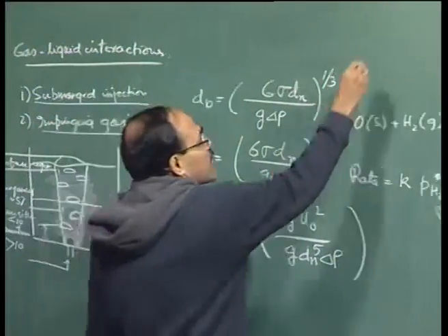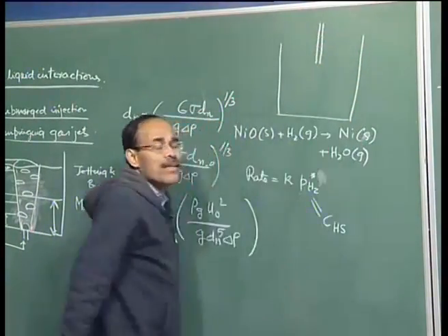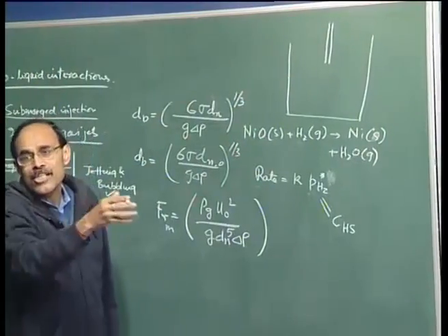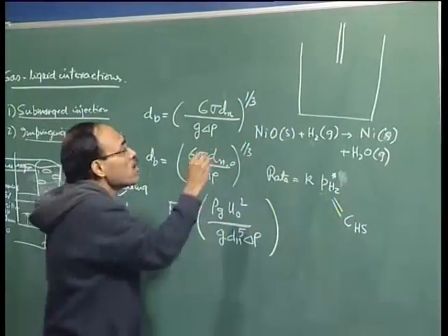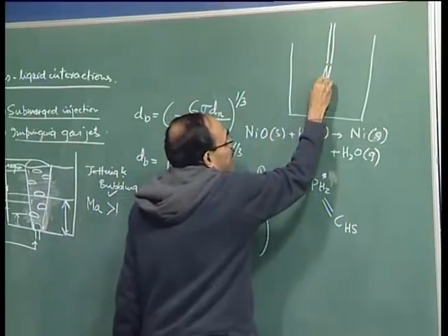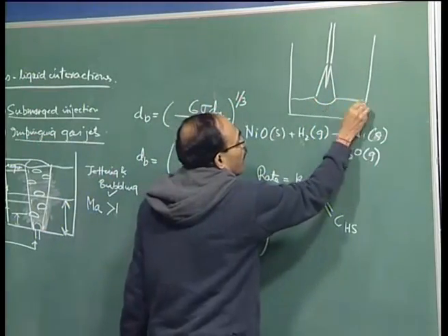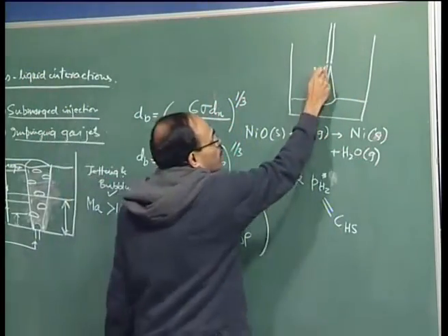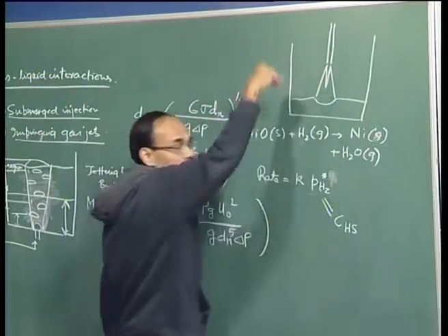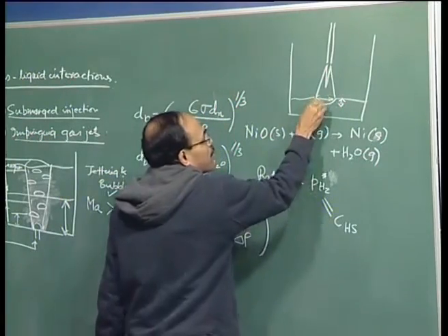Finally, very briefly, about impinging gas jets. When you have impinging gas jets on a system, for example a nozzle, particularly in an LD converter, you have different kinds of nozzles, such as a tube and then a 6-hole lance or something like that, which distributes onto the molten metal. There is a core of the jet, and following the core you have large scale entrainment, so considerable widening of the jet takes place, and this widening of the jet ultimately impinges here. By controlling the height of the nozzle, you can control the depth of this penetration, as well as the impinging area itself.